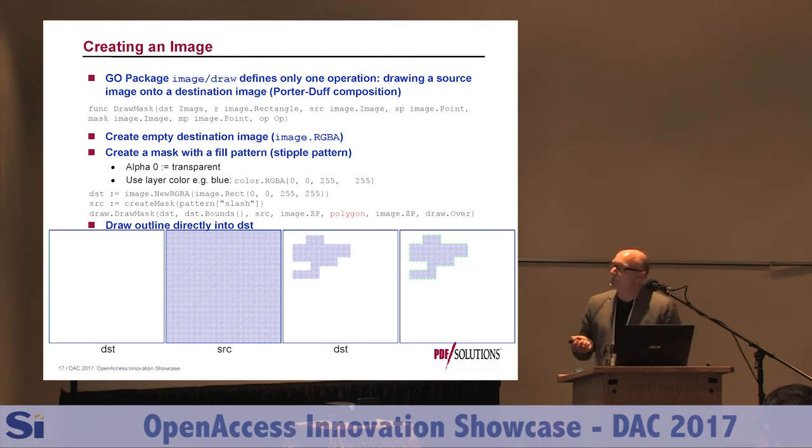Right now I'm reading the display DRF and reading everything Cadence has, and I'm copying exactly the same definition. Luckily, I can just dump it in as is. I can show you later. I can use the exact same definition of the stipples as Cadence uses. It's just a matrix of ones and zeros for transparency versus non-transparency.